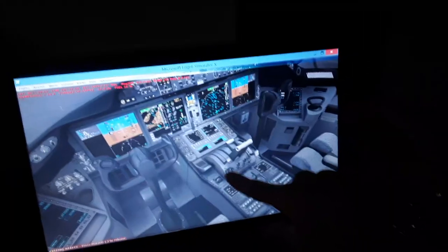It has the auto trim system to trim automatically the horizontal stabilizer and the horizontal elevator. We can trim also manually, so we have the flight control computers channel and we have the manual channel of the horizontal trim stabilizer switch. I will show you now. We have the alternate trim channel. We have also the cutoff switch for the auto trim function of the horizontal stabilizer, so we can use only the manual trim switch in case we have a malfunction of the system. So you can avoid the auto trim.